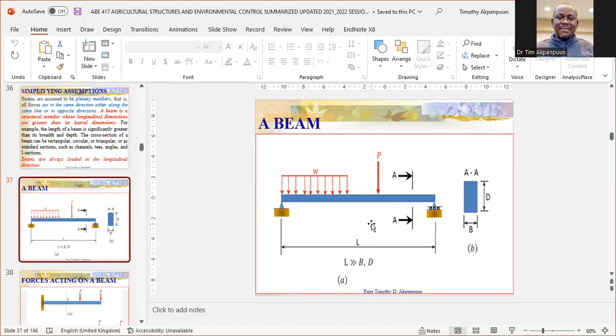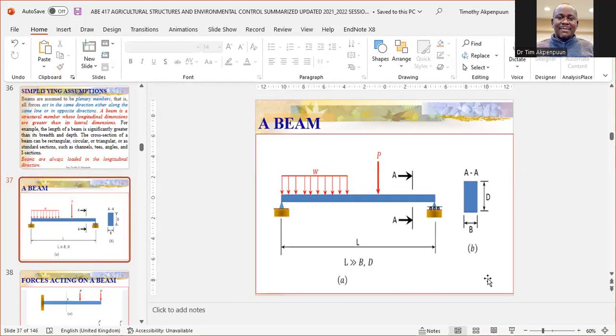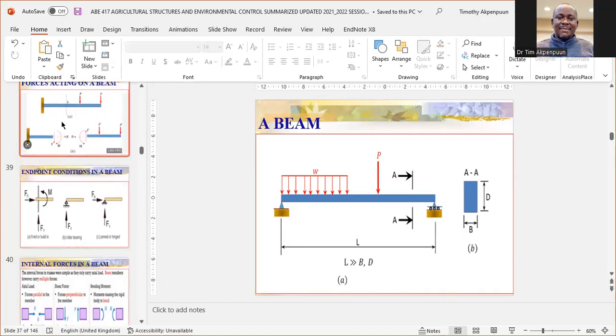And the length of a standard lumber, standard timber? Who can tell us the length of a standard timber? It's 12 feet. Simple. The 2 by 2 means the surface dimension. That's what they call it. 2 by 2, not the length. You don't go and say 2 by 2 by 12. No, it's 2 by 2, and then 2 by 4. The length is assumed to be the same, so it's 12. So a beam is a member whose length is larger than the B and the D.